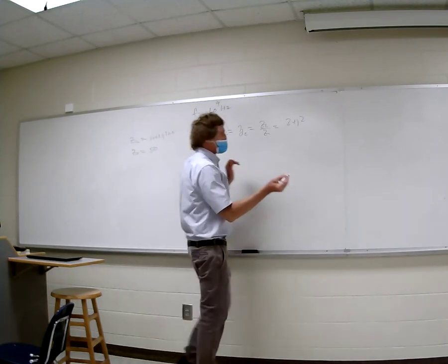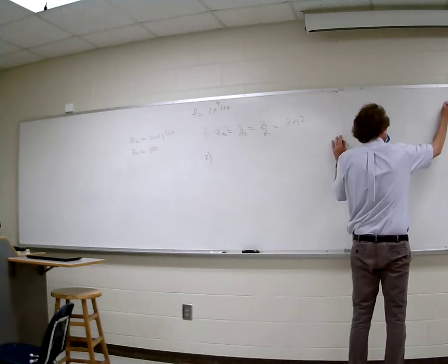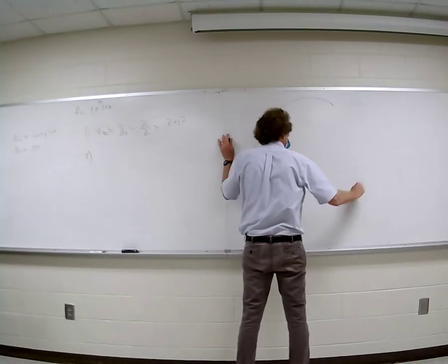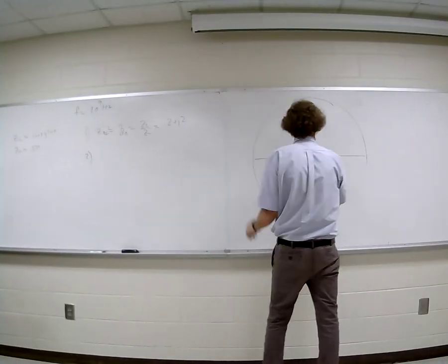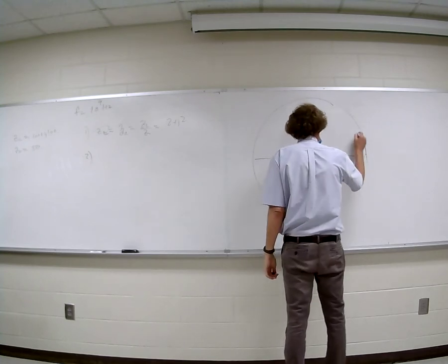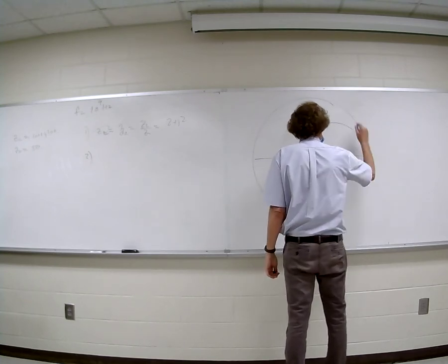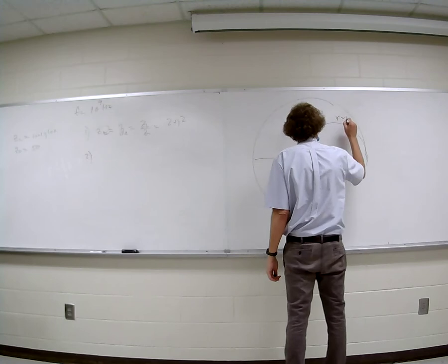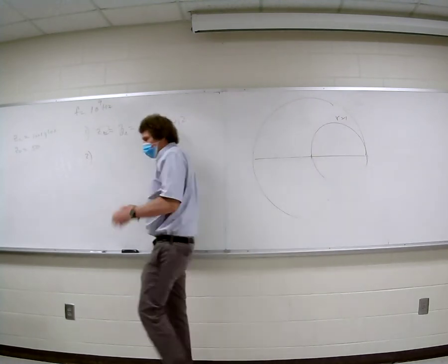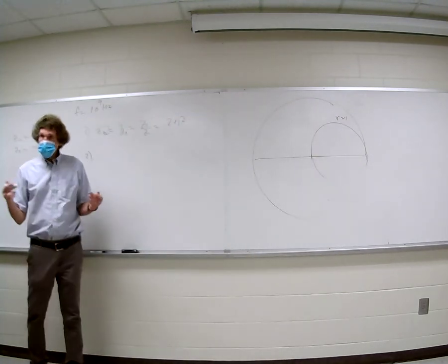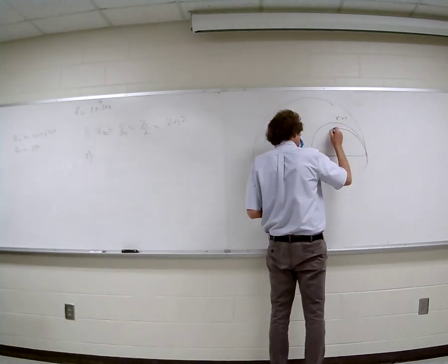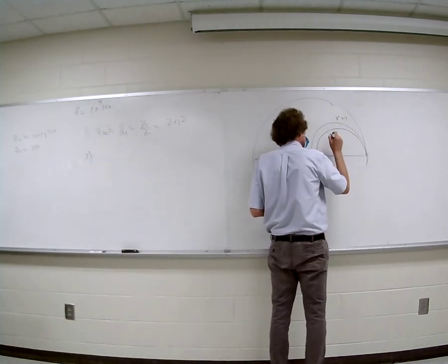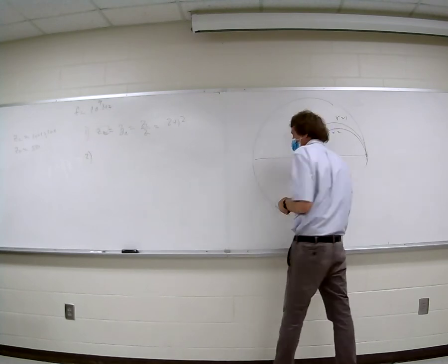The second thing, we're going to draw a Smith chart, and I sketched these things freehand. You have Smith charts, but the way I do this usually is I put the one circle in, and everything else I know where it falls. So R equal 1, R equal 2 would be about here if you look, right? Take a look on your Smith charts. Can you all see that?